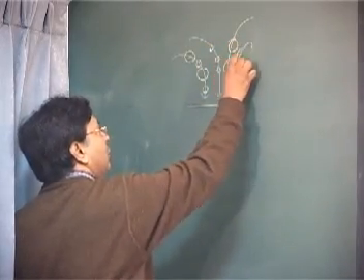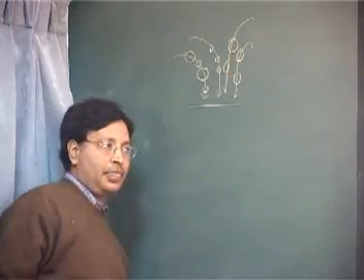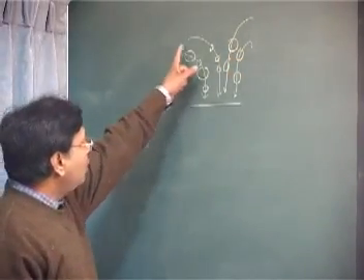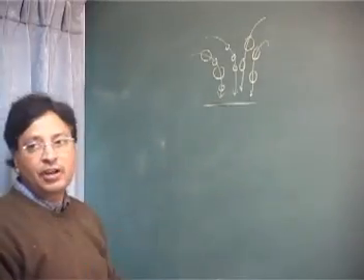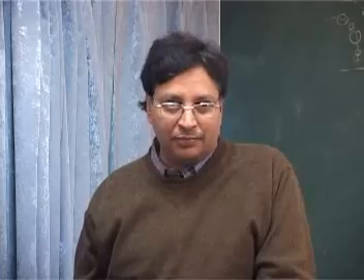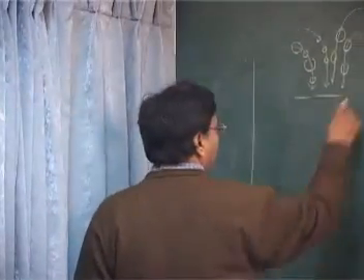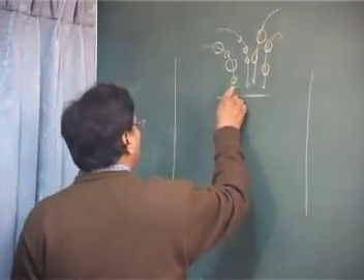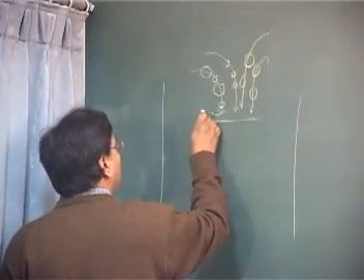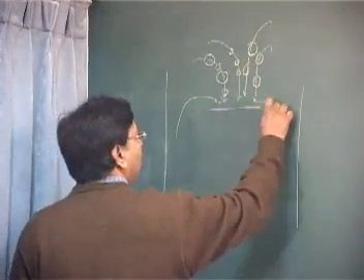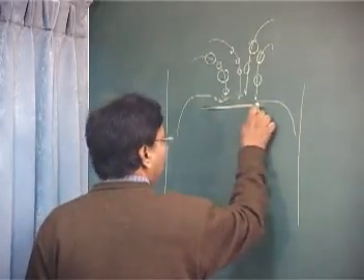Both the particles and the gas stream have inertia, right? Who has more inertia? The particle has much larger inertia, whereas the gas has very little inertia. So the gas streams will try to turn and follow, going beyond this plate.